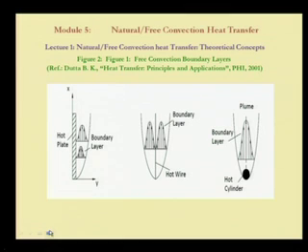Similarly, this is another figure. Here we can see that it is a hot fluid, and the boundary layer is just the reverse of the cold fluid. In the cold fluid we have that in the boundary layer. So, this is the boundary layer and this is the stagnant region, where there is no flow. Again, this velocity profile will be like this, and we can also understand that the flow will be laminar from the initial stages, and as we go along the length of the plate, like we have seen in forced convection heat transfer, it becomes a turbulent flow.